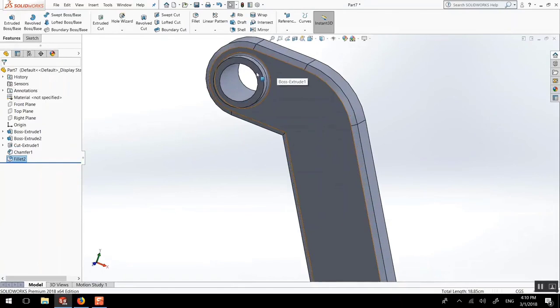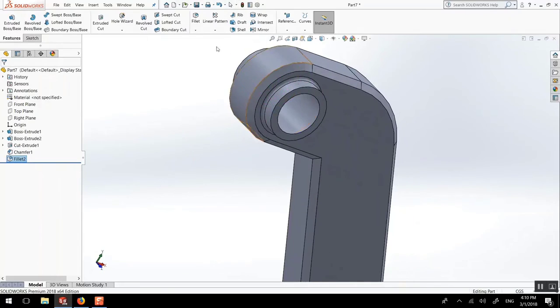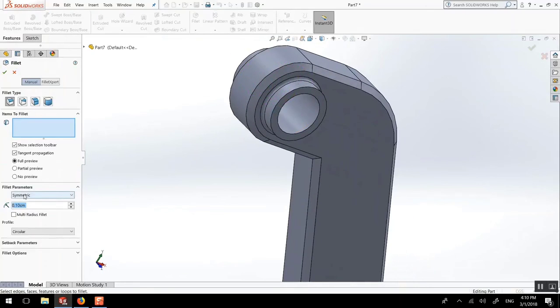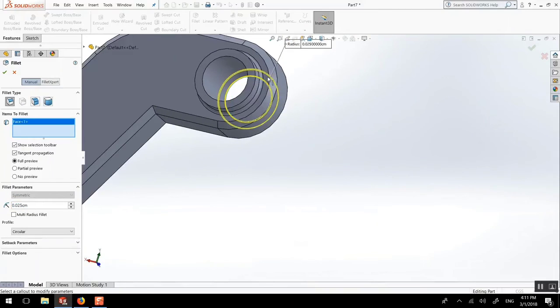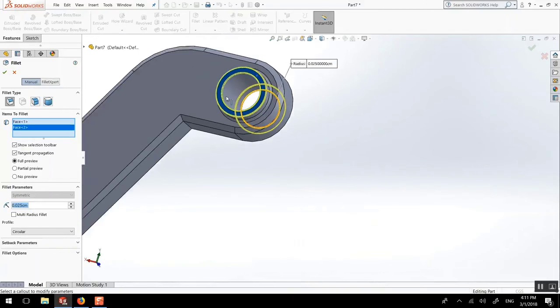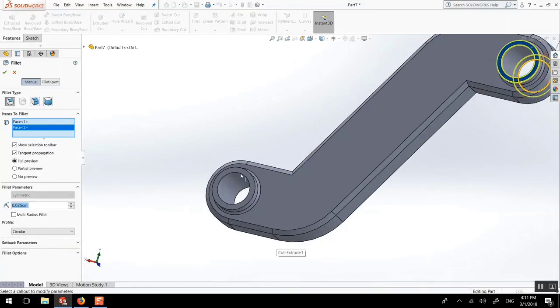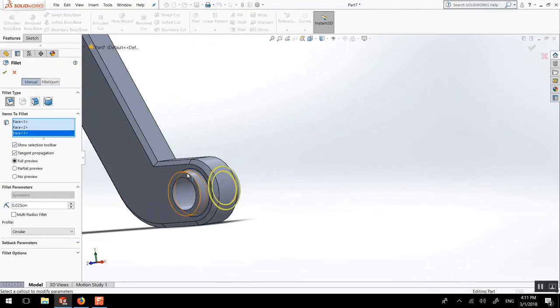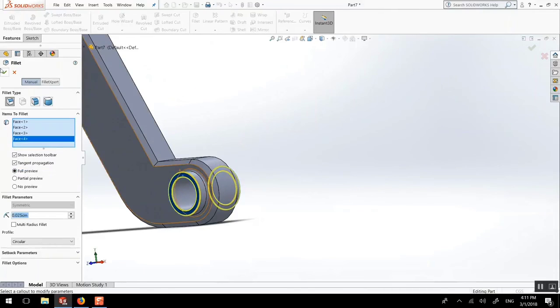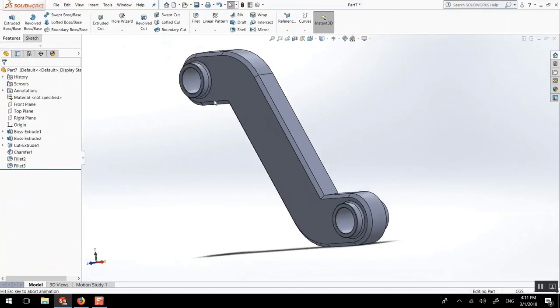And finally, if we really want to do a nice rendering, we could do a really small fillet, like 0.25, and we could do it there on this face. Especially if you're going to use metal for rendering, that could help. For machining, this is not necessary. Voila.